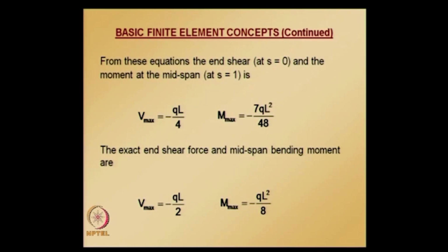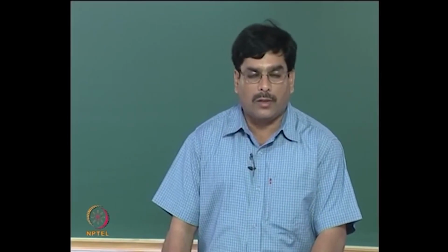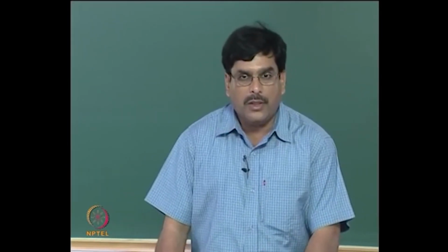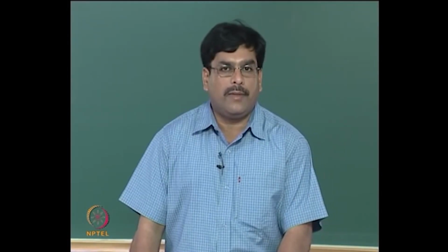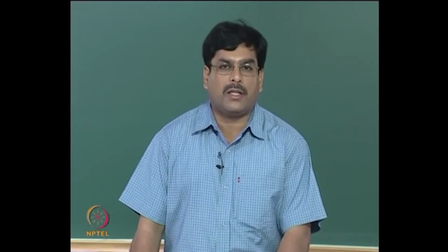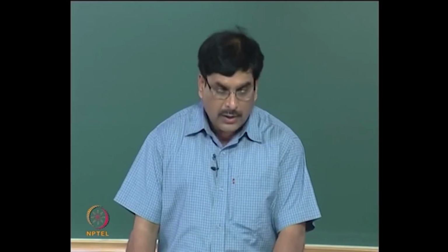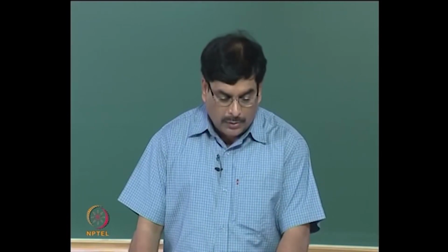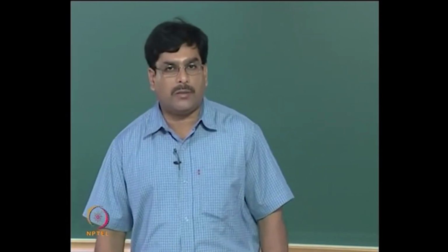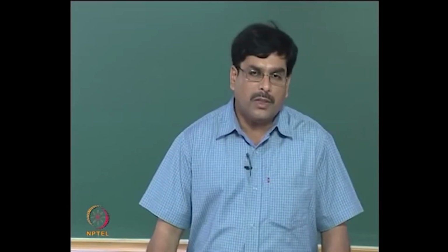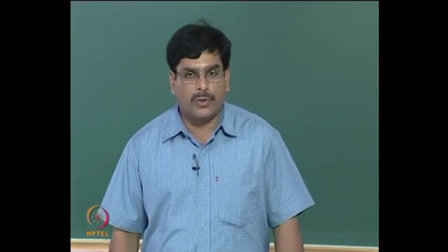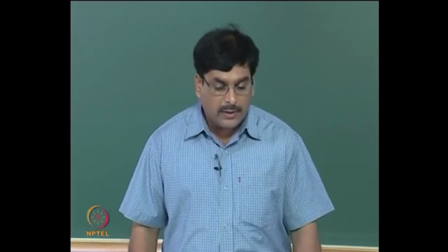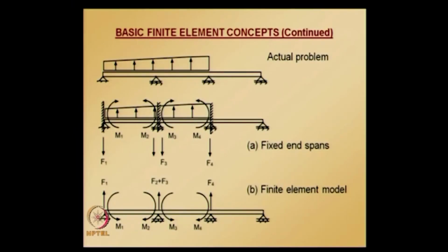Now, the solution that we got using the two element model for the simply supported beam subject to distributed load, even though the displacements are accurate, has inaccurate moments and shears. So, one solution is to use a large number of elements, but that is not a smart way of solving the problem. The other solution is the superposition technique, so we will be looking into it now. Let us assume the first figure shows the actual problem,